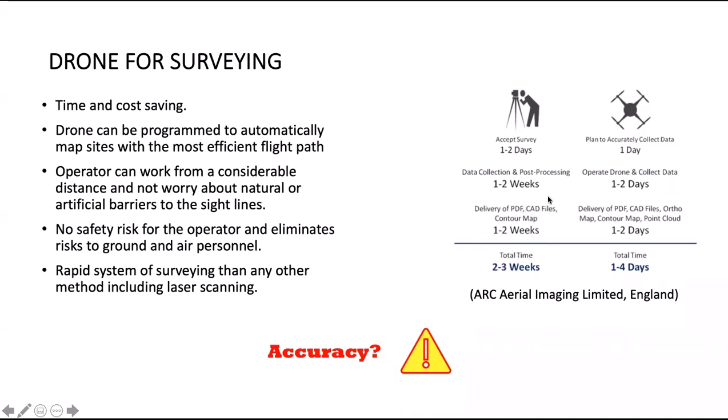So generally it will take 2 to 3 weeks. Okay, so this is the same survey, comparing the same type of survey. With a drone, planning to collect the data will take like 1 day. Operating a drone and collecting the data takes 1 to 2 days, and delivering the PDF or even 3D models and point cloud will take 1 to 2 days. And the total survey can be done in 1 to 4 days.